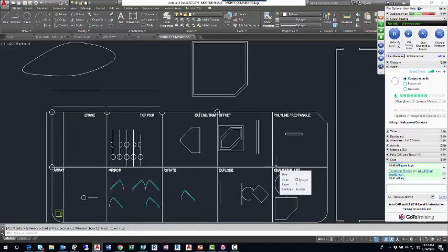And those are the commands that we'll need to create to get this floor plan started. Right, rectangular polyline, offset, explode, more offset, trim, offset, extend, and chamfer. So let's get into the exercise. Unless you have any questions at all, I'm sort of monitoring the chat window.